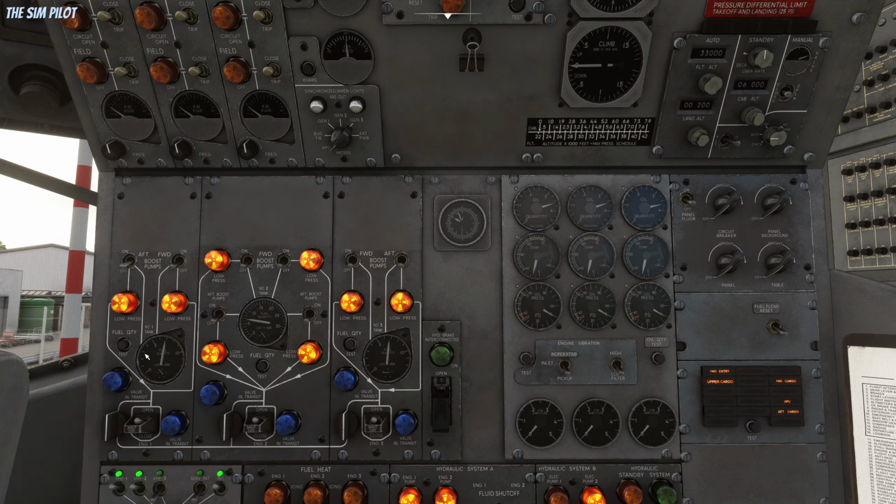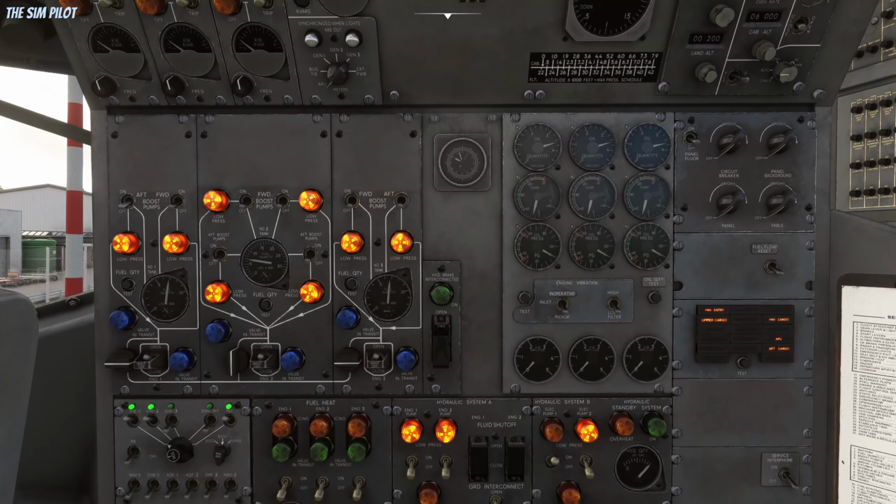So we don't want the wing tanks pumping fuel into the center tank, so therefore we are gonna close the crossfeed valves first to make sure they are operating, check the lights to make sure they are still functional, and then just turn on the center tank crossfeed so that left engine is fed from the left tank, right engine is fed from the right tank, and center tank can also feed the other engines with this valve. So we'll leave it like this.